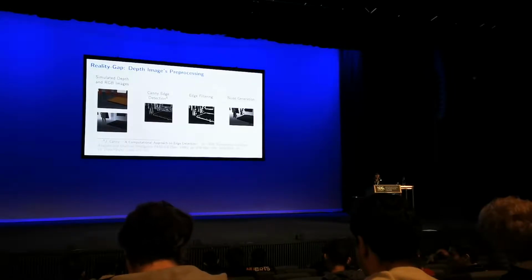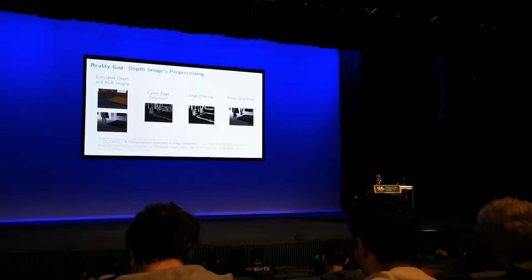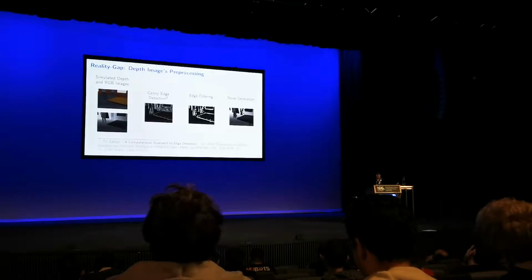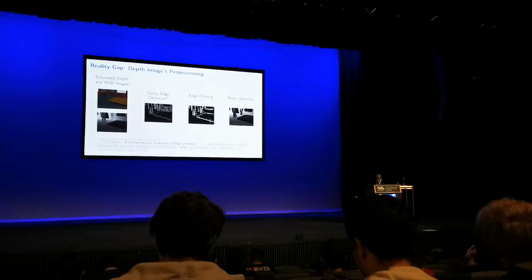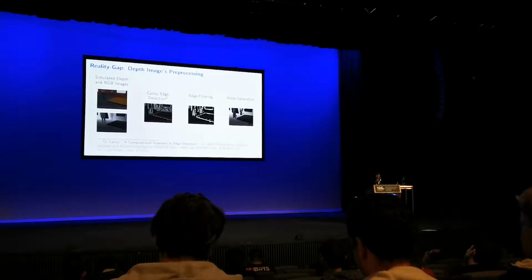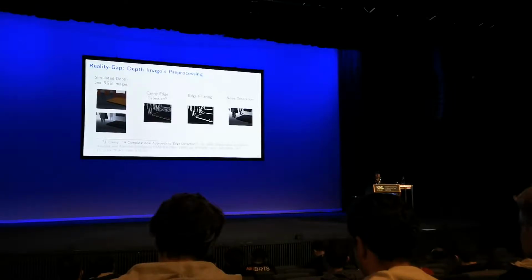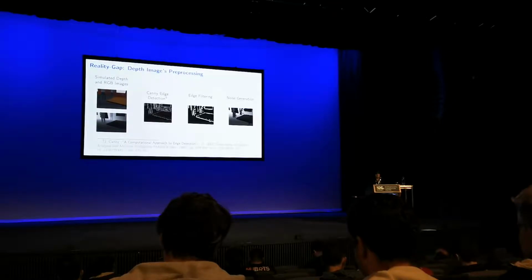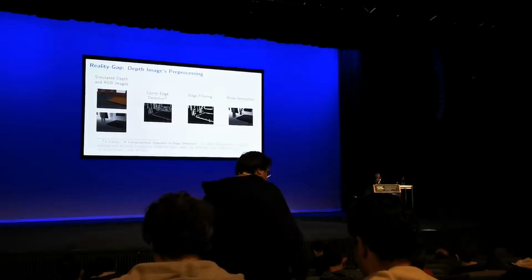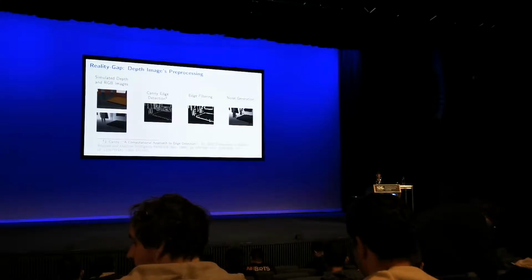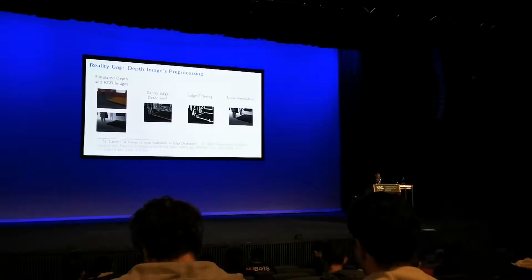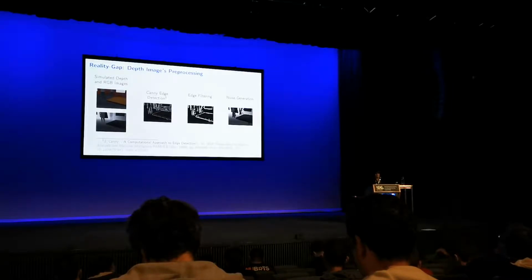So there are several issues with this modeling. First, there is a reality gap between what the robot sees in the simulation and what the robot actually sees in the real world. So we have to tackle the reality gap problem here, and depth images coming from the depth sensor inside Pepper are often really corrupted, even in indoor environments, and there is a lot of noise, mixed and lost pixels, and as it is hard to recover that information, we opted to corrupt ideal images coming from the Gazebo simulator to make them more similar to the actual images that the Pepper robot sees in the real world.